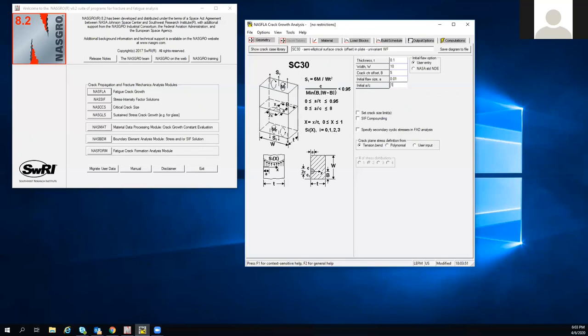So in those cases, the curvature is so slight compared to the size of the flaw. And in this case, we're looking at a flaw that's 1/100th of an inch in depth. So with a radius of curvature on the order of 70 to 80 inches, feet of radii, that curvature would have negligible impact on the geometric factor. So it's a really good point.